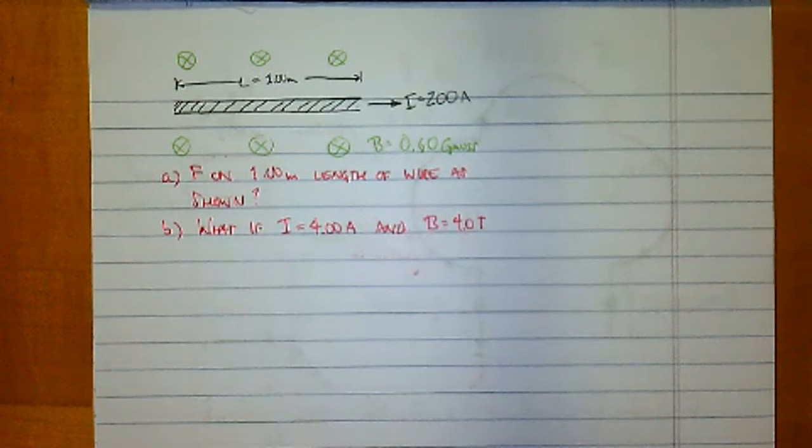But because they don't want to waste so much money on I squared R heating, that is, power equals current times voltage, or if you take into account the fact that you really can't control how much the voltage is going to drop, because it's basically just a function of how far the wire has to run, you can end up getting I squared R by replacing the V with IR. So the power equation, instead of being P equals IV, becomes P equals I squared R. And what you see is the larger the current, the larger the power loss. In this case, doubling the current would increase the power loss by a factor of 4. Tripling it would increase it by a factor of 9, and so on and so forth.